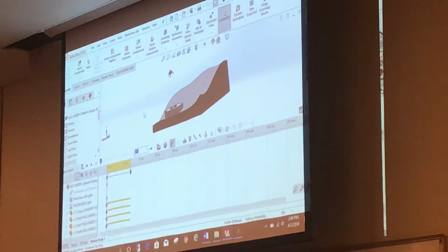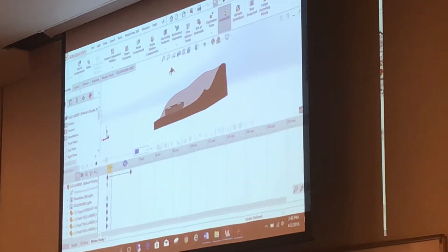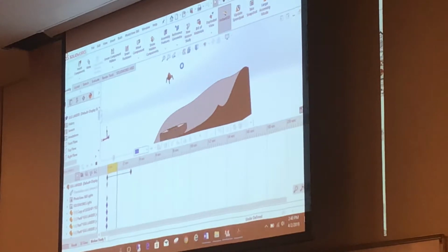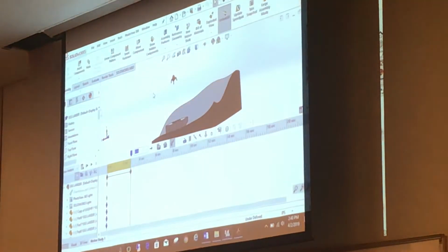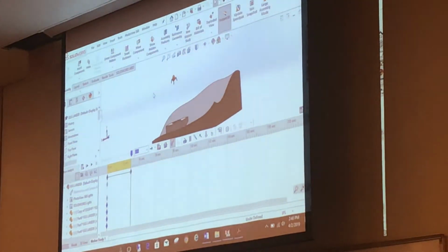And the way that we run motion analysis is click the button right here that says calculate. Okay, so if I click calculate, you'll see it's running through the timeline, but in our model, nothing at all is happening. Okay? And the reason we don't see anything happening is because we've not defined gravity, we've not set up anything that would cause motion to occur. So one of the first things we need to do is turn on gravity.